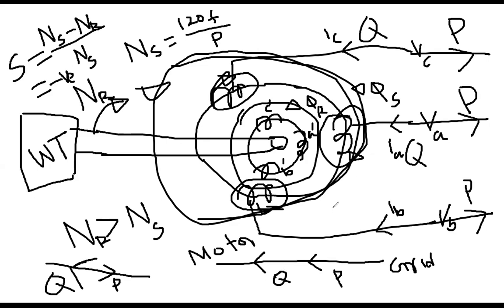Sir, in case of induction generator, the reactive power is needed continuously to pump back the active power. Yes, always you need it, because you need magnetization. There are no physical poles here. That's why you always need the Q. And it is called the Q because these are basically the coils, so the coil will absorb the reactive power.